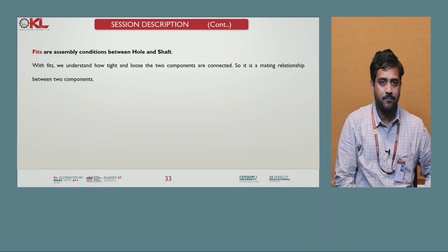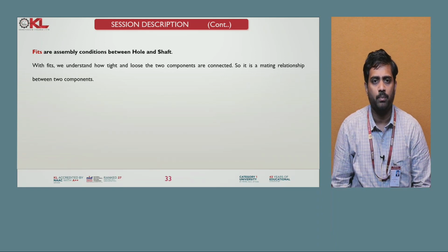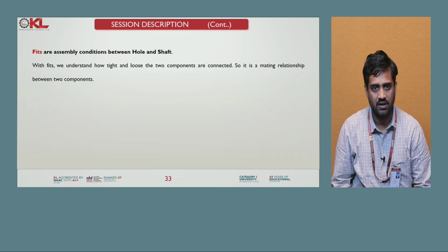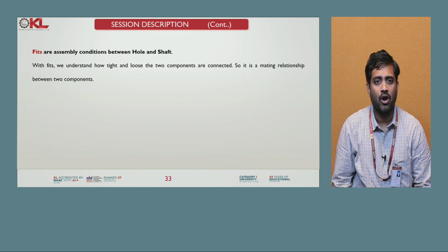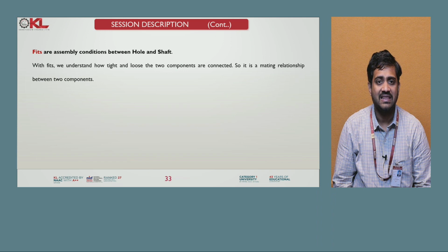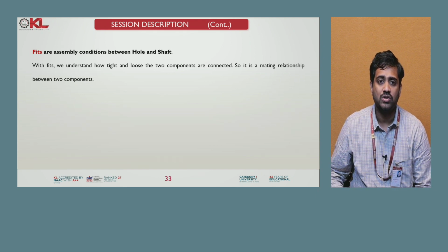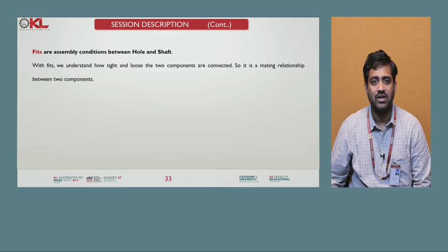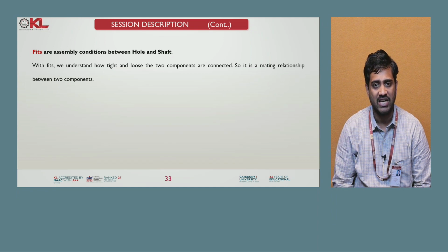For example, take the two components, hole and shaft. Whenever a shaft is inserted into a hole, if the clearance is minimum, then a thin oil film can be maintained between the hole and shaft contact, and the shaft can slide freely with a minimum clearance.